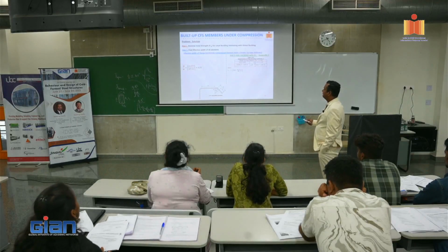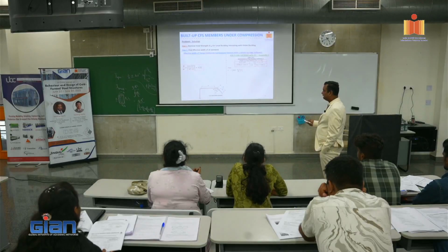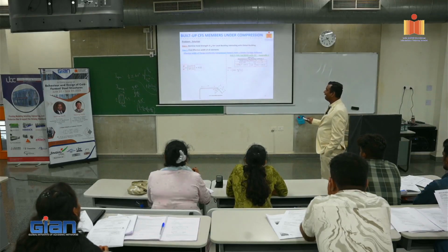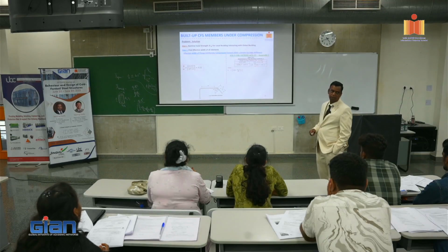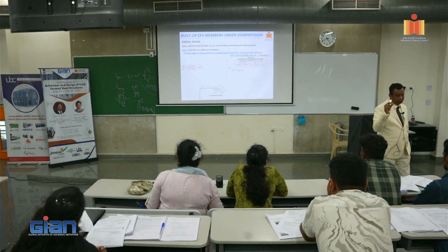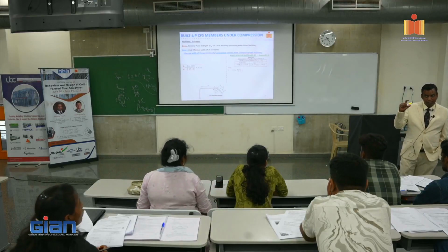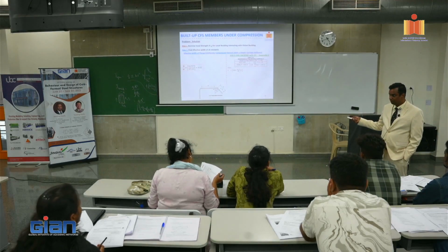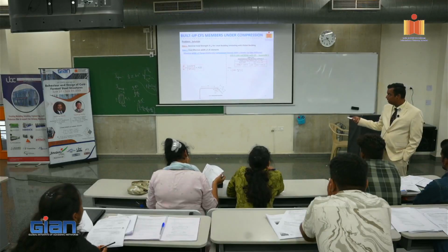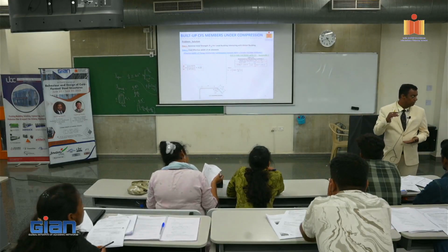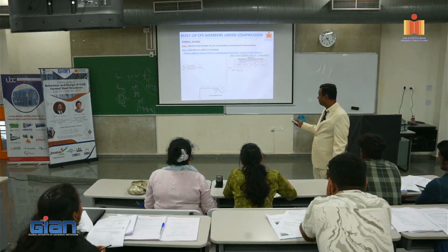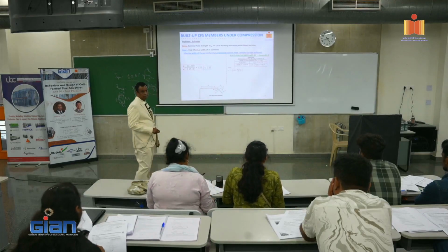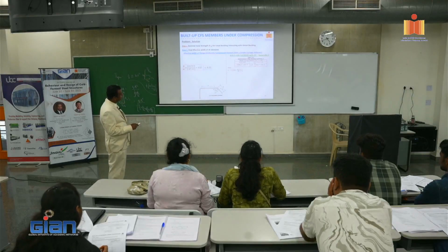So d/w is 0.22. d is the depth of the lip, and w is the flat width of the flange. This is not the flat portion, d is the full depth, minus just the coating thickness you are taking. So don't get confused. Don't reduce the corner radius for this one, as per the code. Many people make that mistake. Don't take the corner radius out. Here the corner radius is included, which is the total depth of the lip divided by the flat width of the flange, which is 0.22. Now this is less than 0.25, so I have to use this equation here.